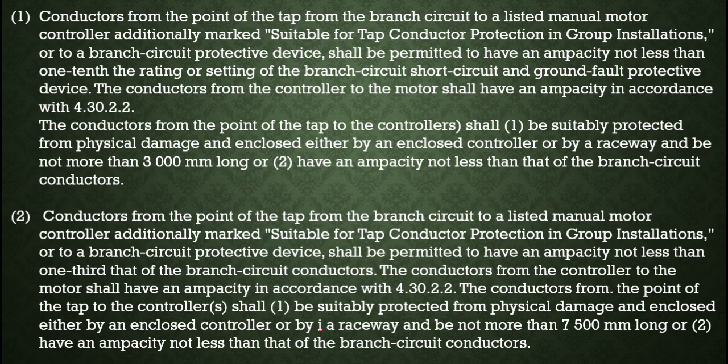And also, the tap conductors must be protected and enclosed, either by an enclosed controller or a raceway, and have length limits. And conductors from the tap to a listed manual motor controller can have an ampacity of 1/3 that of the branch circuit conductors.